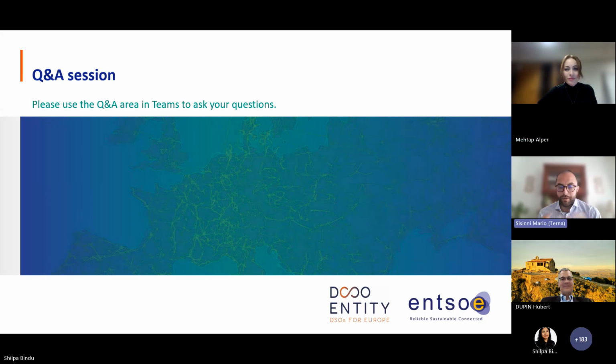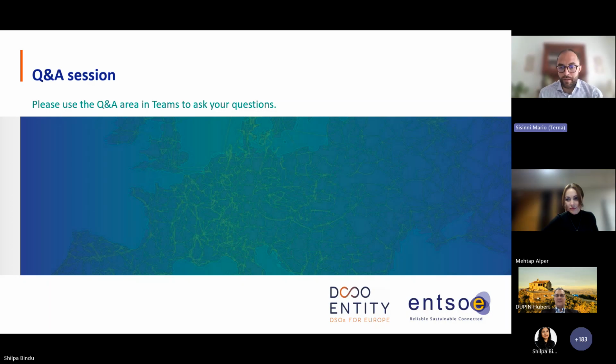Yeah, I'll try to answer this, although it's a bit complicated, so I'll try to be quick, but of course we can further discuss. This very much depends also on the type of approach which is used for the quantification, especially for the RES integration need. Because you probably saw the slide in which I was describing the three different approaches. You can start from the ERA, from the national adequacy assessment, or you can run a separate economic dispatch simulation. So it's obvious that the possibility to run a separate economic dispatch simulation was exactly introduced to facilitate this quantification of the RES integration needs and also the modeling of different technologies.